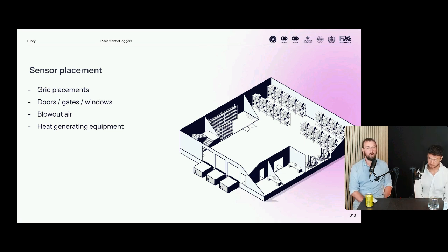Another thing we see are office facilities. Those will also create heat, and it can be one of those things that if you do an initial mapping of, let's say, a warehouse, it's often not with the people working there. They won't be sitting there with their personal computers, their screens, their monitors, everything. And that means you need to be extra cautious, because often we see when performing an initial temperature mapping, it will be without the people having the computers and so forth. So it won't be present in the mapping data, but it's a risk that you should identify when you know how it's going to be used further on.